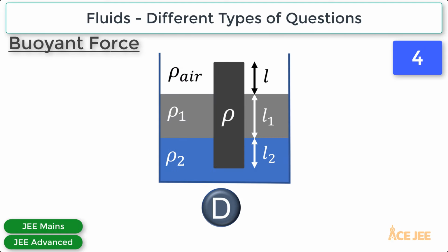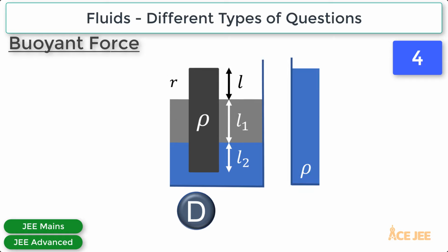In the fourth one, a cylinder might be floating in a container with two or more immiscible liquids, and here you might be tested on your understanding of the buoyant force, which simply is the vector sum of the pressure forces exerted by fluids on the object. Note that the top liquid in the setup shown exerts no net force on the container.